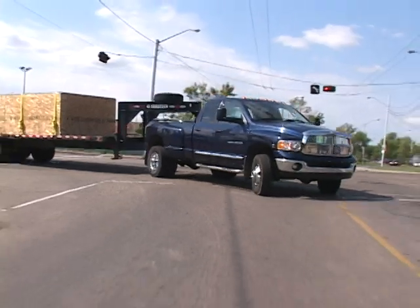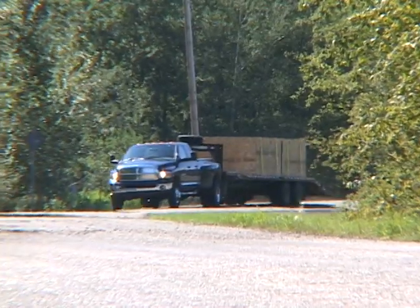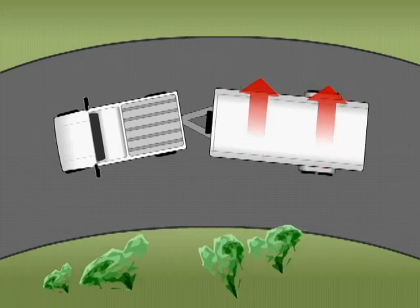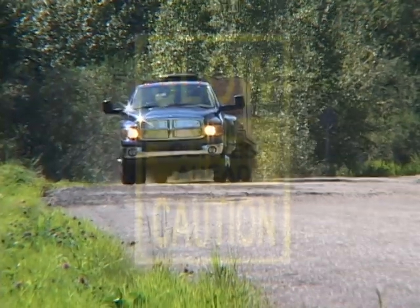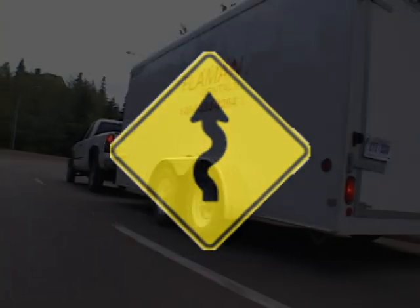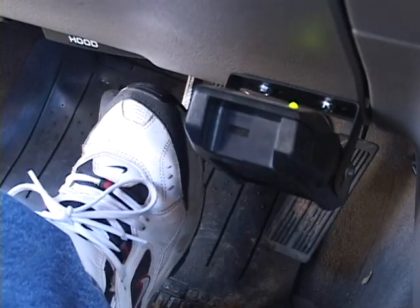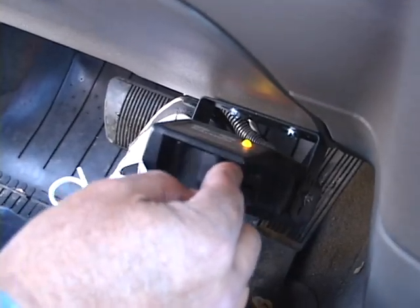It is important to slow down when turning corners or taking curves to prevent swaying or load shift. The faster you travel through a turn, the greater the force on your load, and the risk of your load shifting increases. Pay close attention to advisory signs for curves and always slow down before you enter a curve. If swaying occurs, steer as little as possible while you slow down. Application of the trailer brake usually tends to help keep the vehicles aligned.